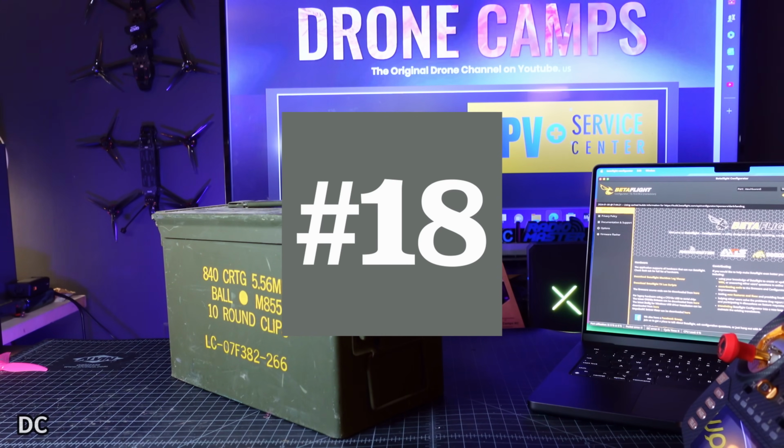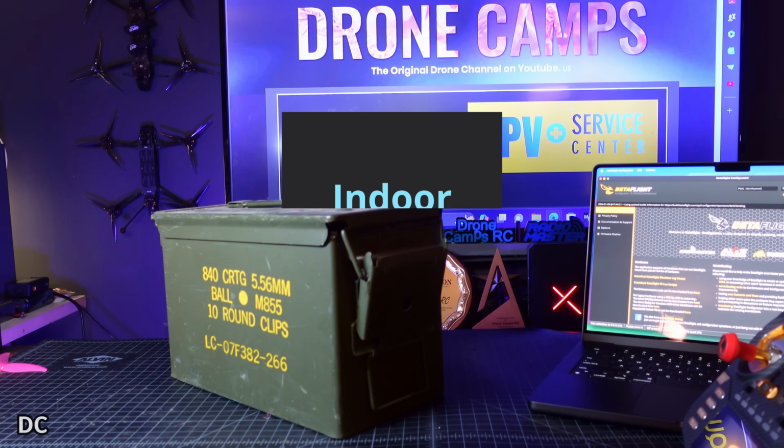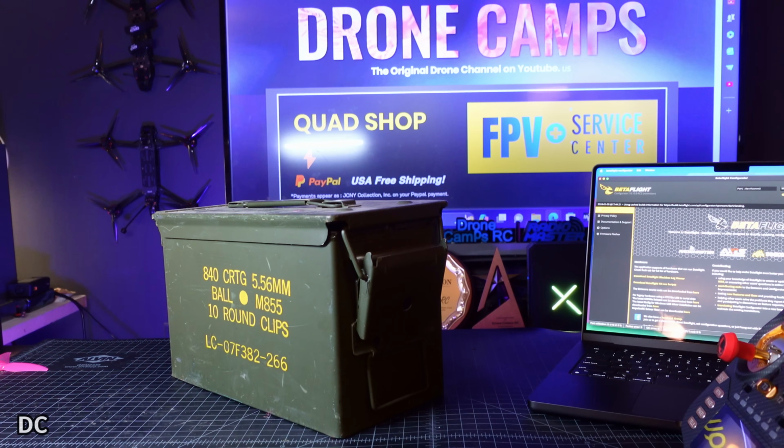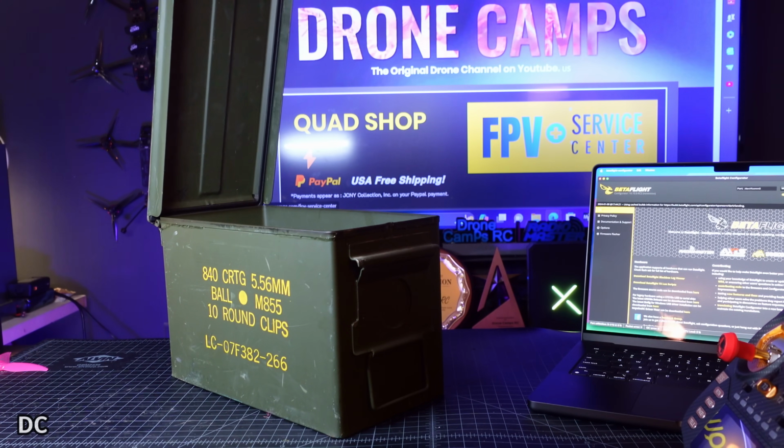Now there are several ways you can safely store LiPos indoors in your garage or in your house to give you a little bit of a safeguard from fire. Now the number one choice for many people for many years, and this comes from the RC airplane crowd 20-30 years ago, is using ammo tins. I was one of the first drone channels to talk about this.